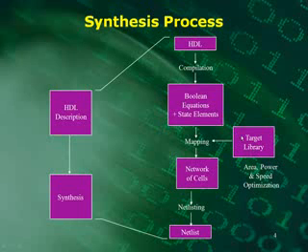So you might be thinking, well, what do they have in the target library? Let's say that in your equations you had a function that required an 8-input AND gate, and the physical FPGA doesn't have an 8-input AND gate. The target library would know that the maximum it has is like a 6-input AND gate. So it would take a couple of AND gates and build an 8-input AND gate based on the target library. So the target library is a real physical thing that we're going to want to produce too.